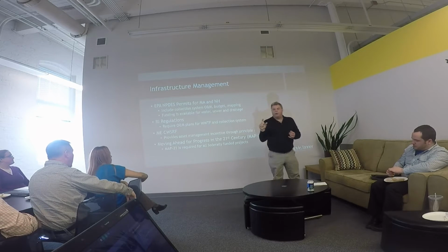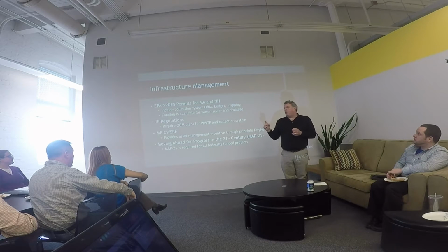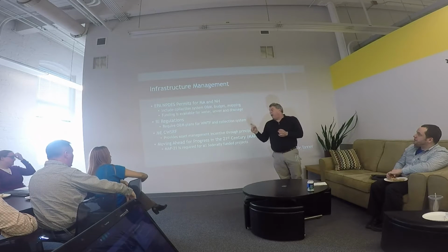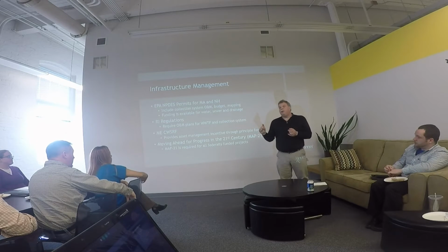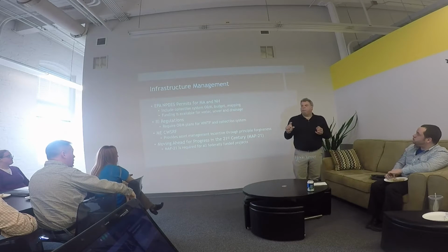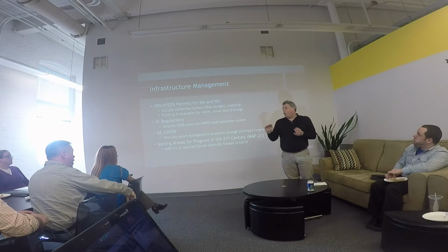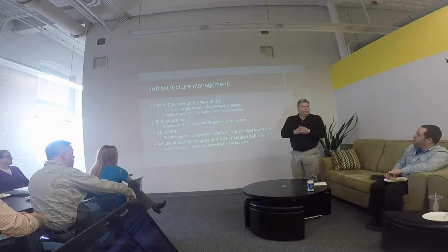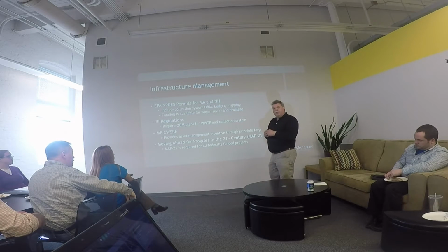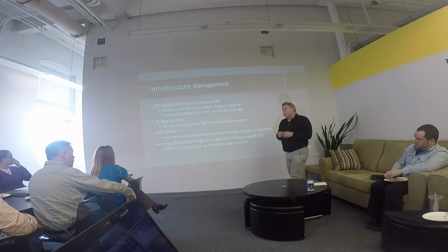The performance measure for cleaning catch basins is no longer we want you to do it every year. It's now when the sump is half full of sediment. We want you to guarantee that you're going to clean that catch basin no less than when the sump is half full of sediment. How's the community supposed to track that if they don't have some kind of system that they can manage in real time, how they're doing?